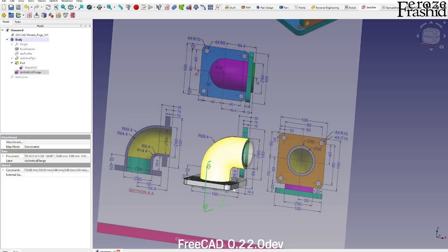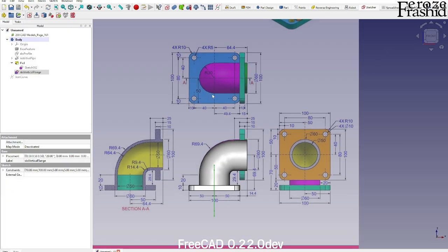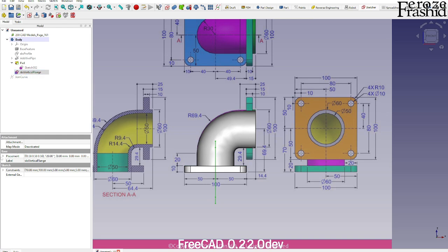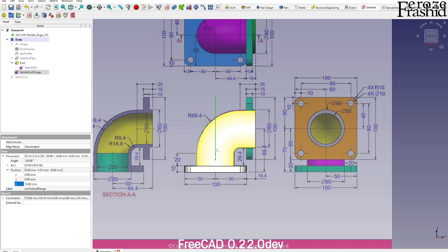We can see that. How about I relocate that right now before we do anything drastic? So on Z, I want to move it up, so the height is 70, right there. So this is the height we want, and I want to move it sideways by 50. Okay, so on X it would be 50. So we got it located.